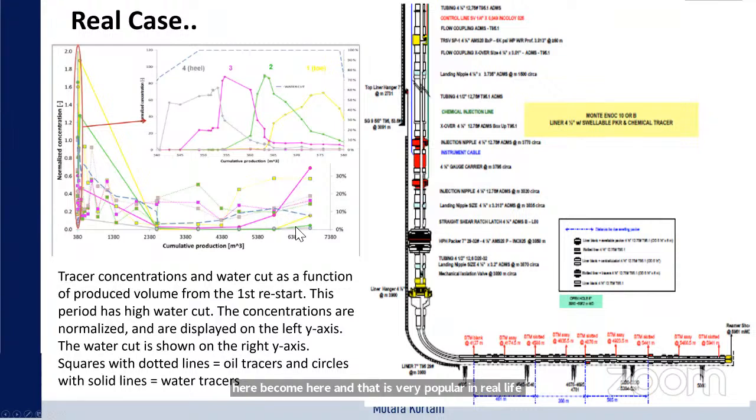According to the pressure signals and the performance of the wells, you may have this kind of behavior where the production, especially in commingled production, has no steady state conditions and no steady contribution. The contribution moves up and down among the intervals you are completing or that are open for production.